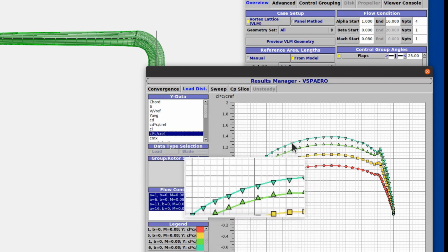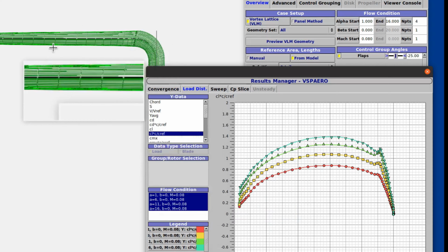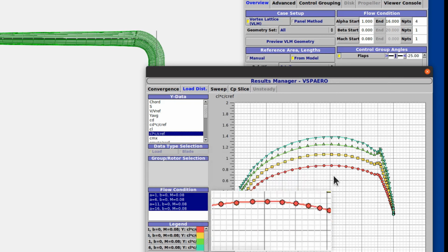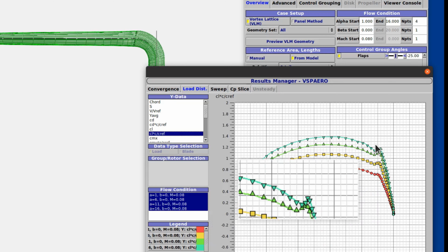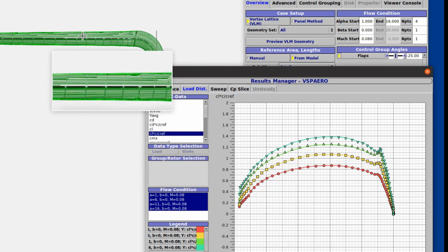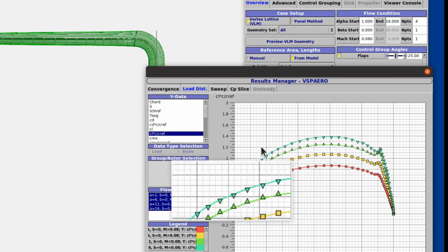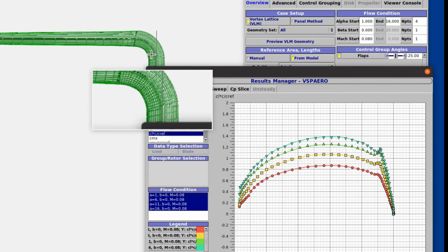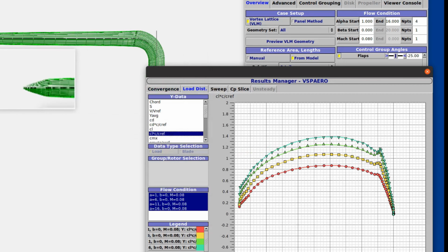So as we increase in pitch, or in our case, beta, we get more sideways lift off of our vertical tail. As we're doing our rudder design and vertical tail design, in calculating how we're going to do the structure to deal with this lift distribution, we're really only going to start here, which is right at this curve, and come out to the tip.